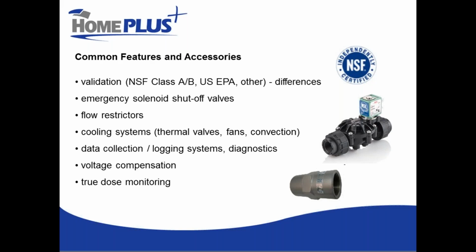Just be aware that for your applications, if you're providing water to a public setting, validation is required to get a construction permit from the health authority. So there are lots of UV models on the market that are not third-party validated. Unfortunately, those are not units that you can consider for your applications.